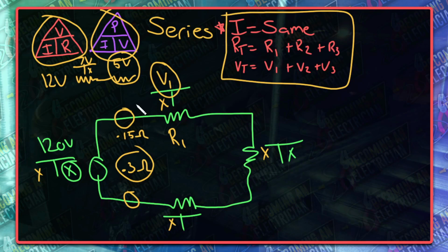Or even like the power coming into the home, because let's say from the transformer outside you're getting 120 volts, but it's a long run to the home. And then by the time you get to the home, let's say it's 112 volts or something. You're always going to want to try to get as close to 120 volts as possible, because that is what equipment is rated for, right? There is always a little bit of variance. And that's where that 3% stuff came in. You're allowed some variance, but typically you want to get it as close to that 120 as possible. So that's just one thing to say, that there is resistance within the wire itself as well.